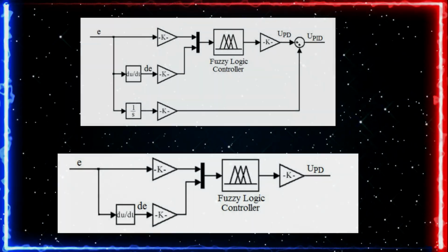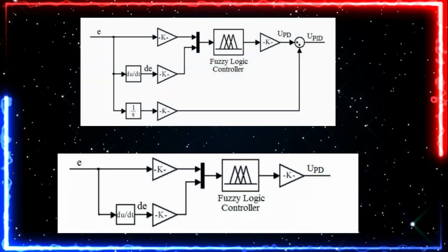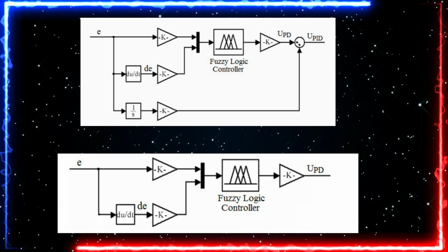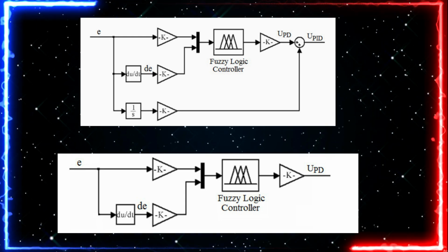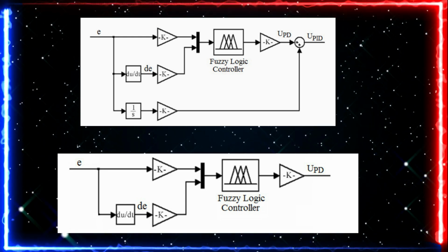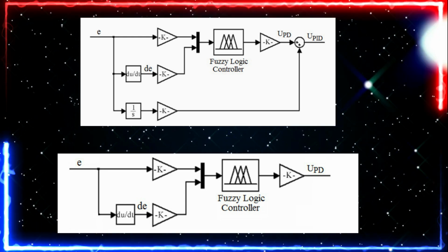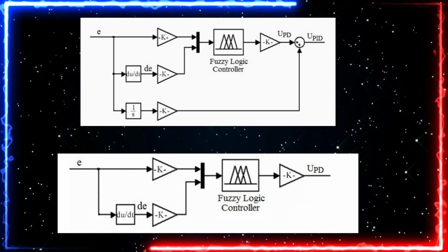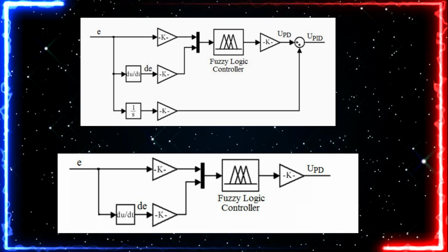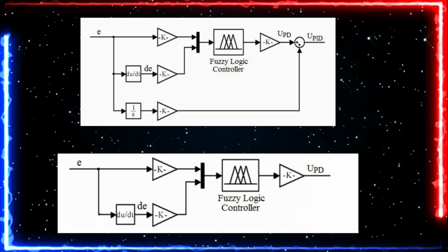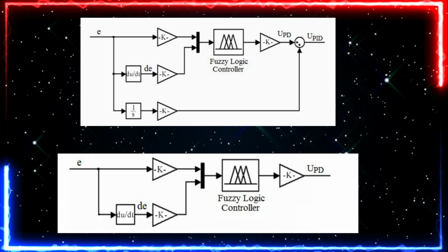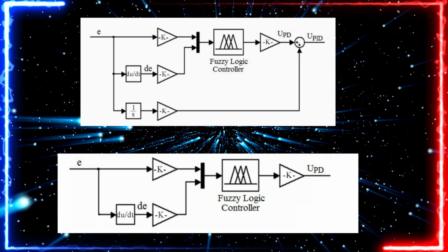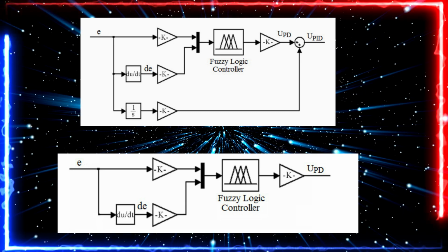Okay, so now, building on the literature review, let's look at the block diagrams of fuzzy controllers. The Fuzzy-PD controller integrates fuzzy logic with a proportional derivative controller to manage errors and their rates of change, improving stability and reducing overshoot during satellite maneuvers. The fuzzy logic processes the error and its derivatives using a set of fuzzy rules to adjust control signals in real time. On the other hand, the Fuzzy-PID controller adds an integral term to the mix, which helps to eliminate steady-state errors by accumulating past errors.